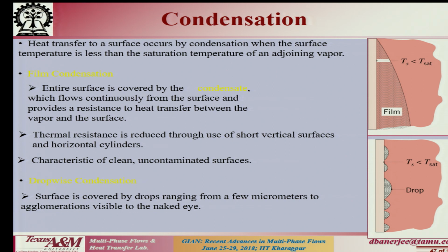So, will the small droplet get inside the big droplet or will the big droplet move into the small droplet? Okay. Why would the small droplet move into the big droplet? Because the sigma by r pressure is higher in the small droplet and flow always occurs from a high pressure to a lower pressure. And so, what happens is the big droplet cannibalizes the small droplet.